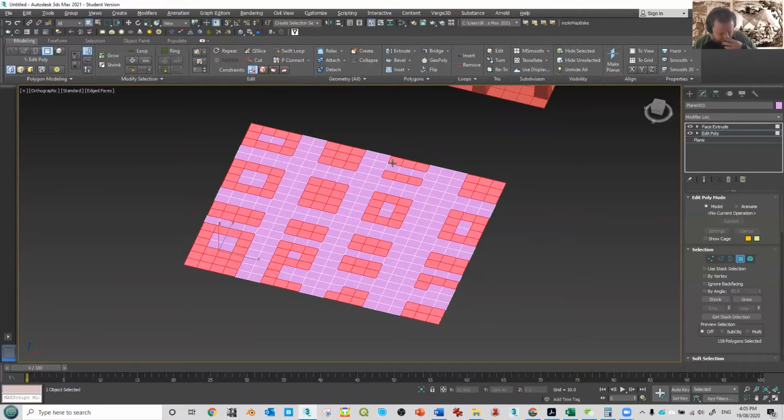I find it's one of the more frustrating things because in most things, like in Photoshop, you hold Shift to add to a selection, and there's a Control for the other. But in Max it's Control to add, Alt to remove from a selection. You could probably edit your shortcuts if it was super frustrating. I'm pretty used to it now.